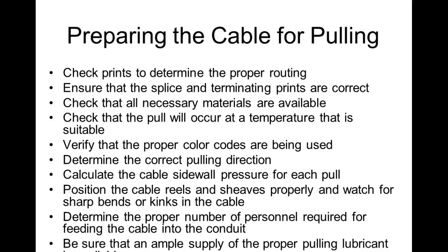Preparing the cable for pulling. Check the prints to determine the proper routing. Ensure that the splice and termination points are correct. Check that all necessary materials are available. Check that the pull will occur at a temperature that is suitable. We don't like to pull at extremely cold temperatures, and why is that? Yeah, well, and also the cable doesn't flex as easy. Extremely hot temperatures means you get more friction on your jackets.